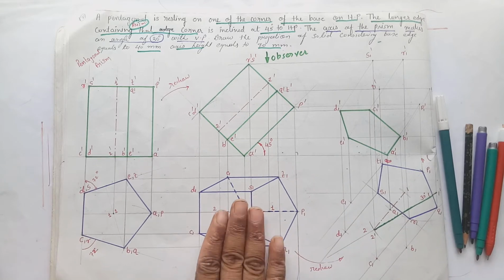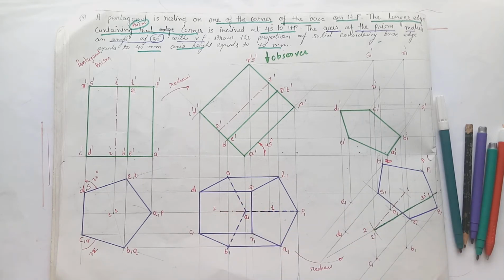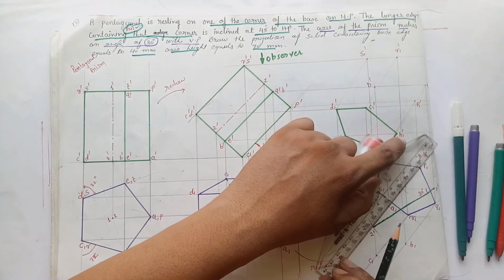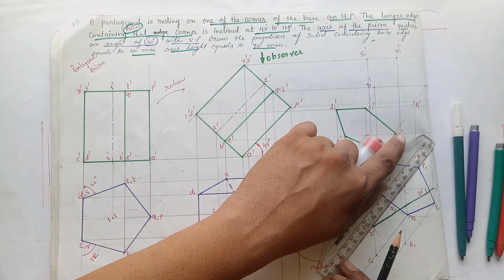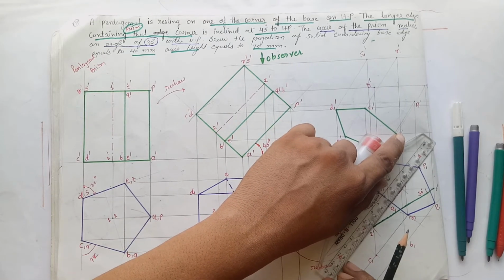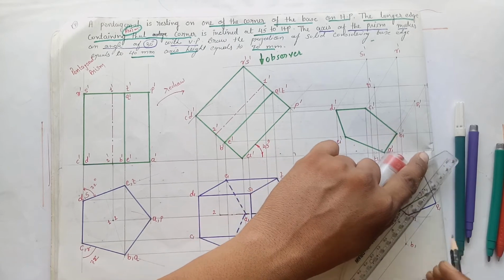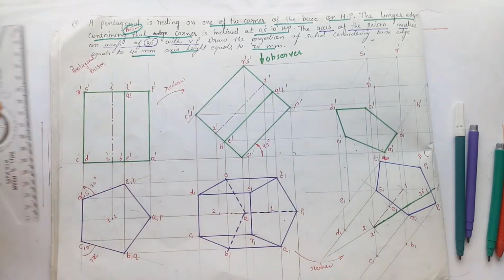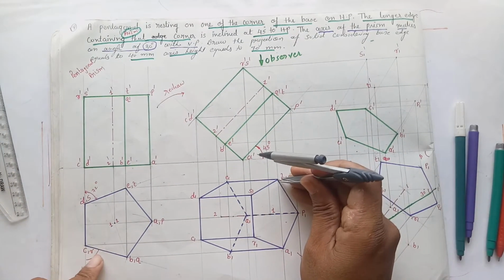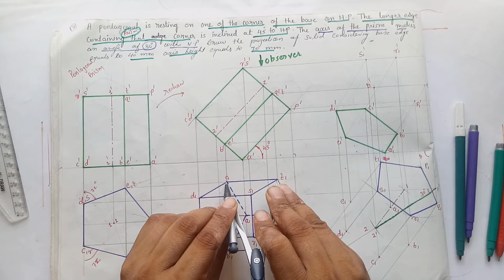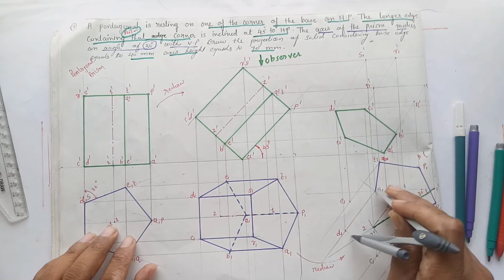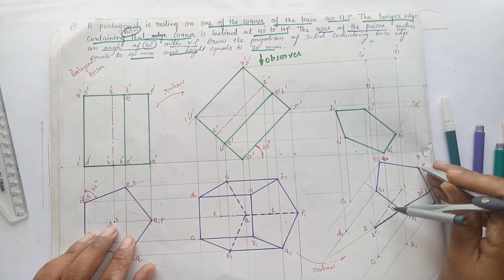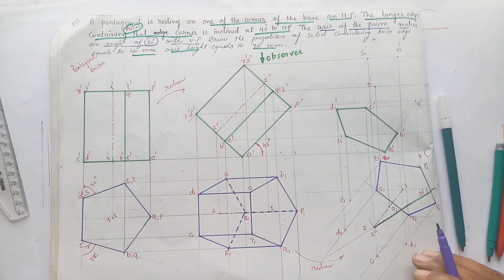After drawing the top face, we have to copy this figure, and if you want to copy this figure over here a little bit faster, then now draw lines parallel to the axis from each of the top corner, that is P, Q, R, S, T. After drawing these lines, measure this distance E to T, give an arc 1, 2, 3, C, P and A, and copy this figure.